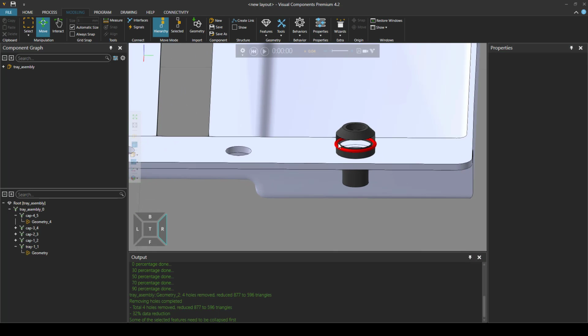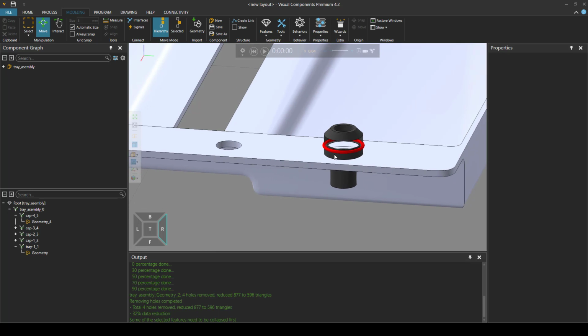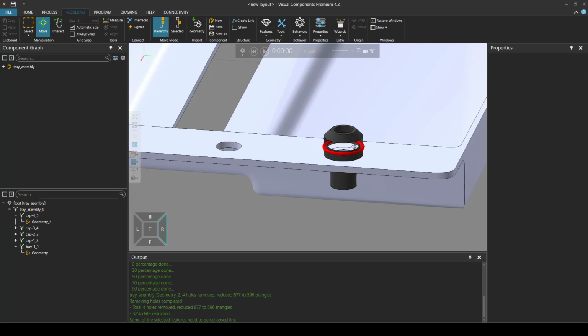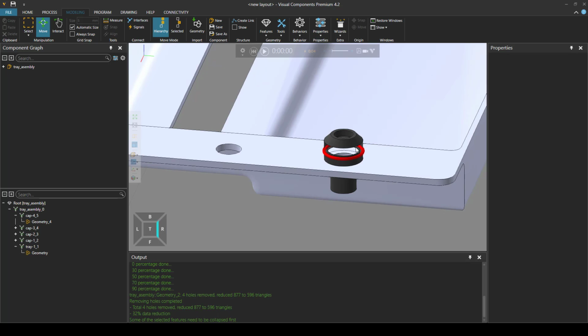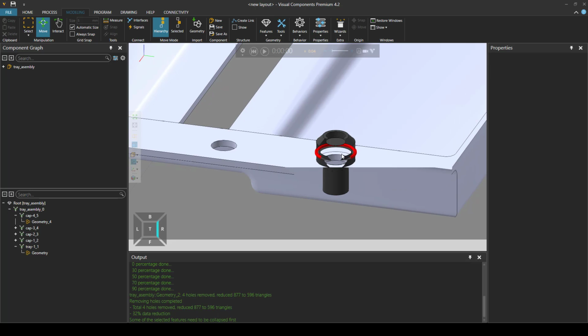So it doesn't render that face, and now I'm able to see inside of this geometry feature through the face that just got inverted. For instance, let's say you have a factory and you would like to see the factory from inside and not render the outside walls. If you turn the backface mode off after you invert it, you should be able to see inside of the factory.